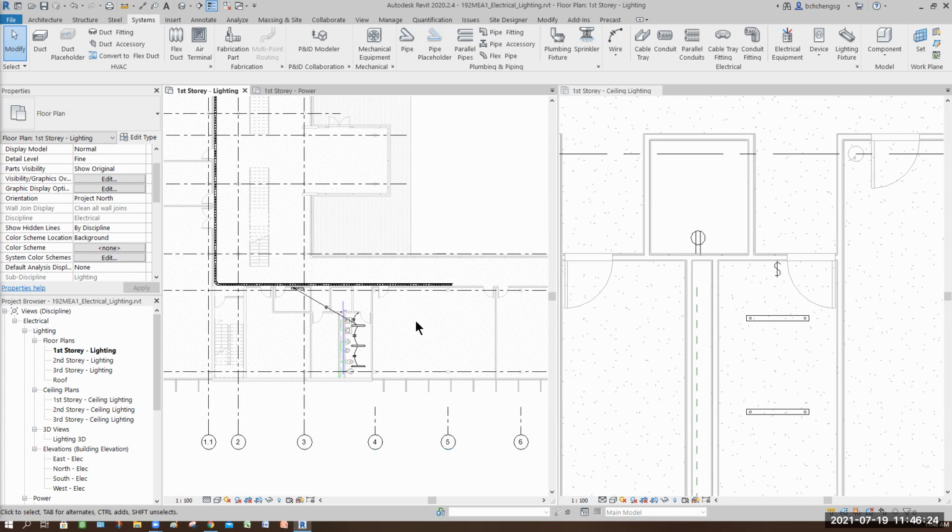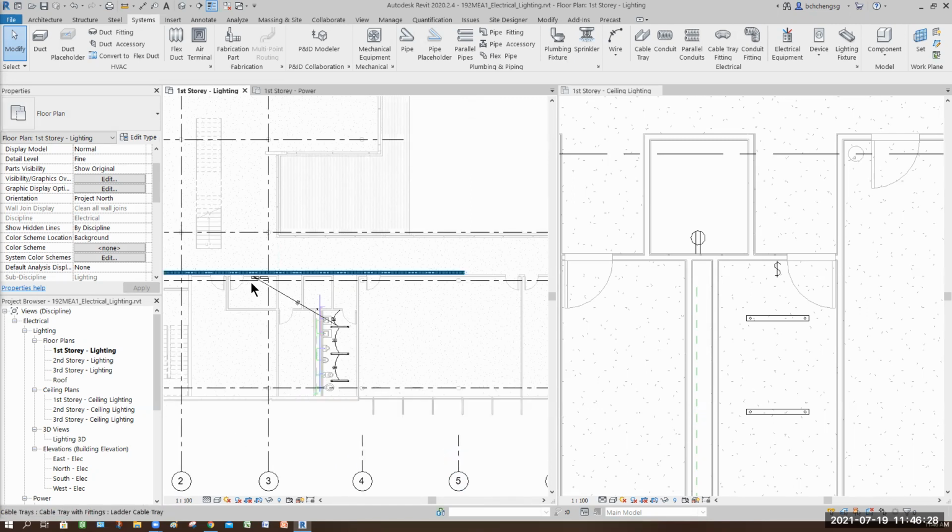If it's a computer lab, I don't think I want the panel to be here. It should be in here, like what you see in BCA, where every room has a sub panel. You get what I mean? Unless you tell me the whole zone's control is at the Fire Command Center, FCC. If not, it should split into individual panels.